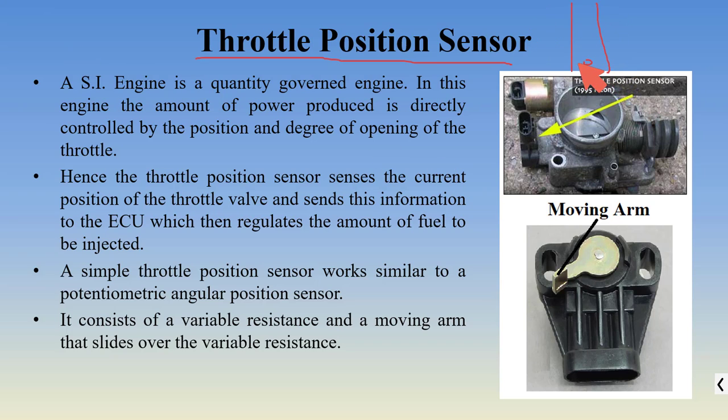Throttle is located inside the intake manifold, in the beginning of the intake manifold. Over here, there is throttle. If you press accelerator less, the throttle is in semi-closed position. If you press the accelerator very much, the throttle will be in open position and all the intake charge will go into your intake manifold. Here only some amount of charge will go.